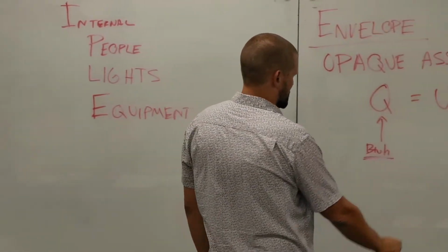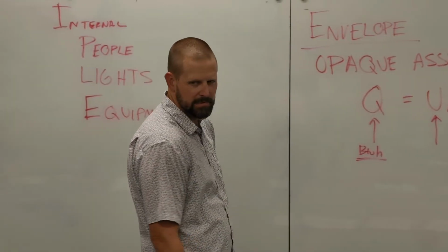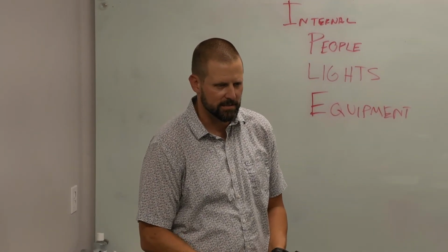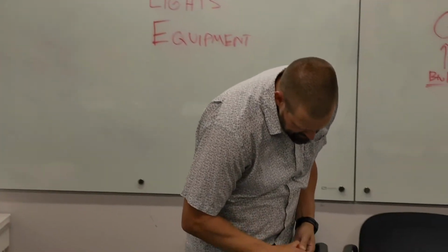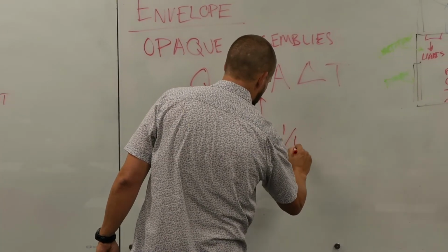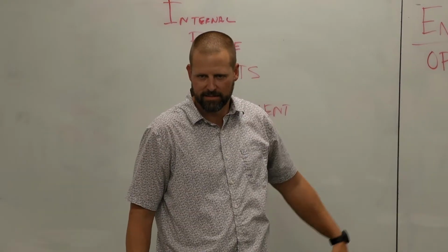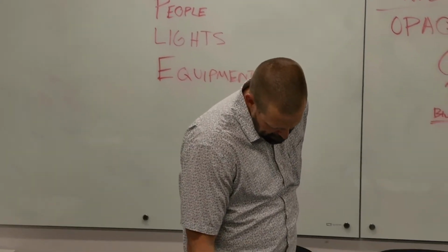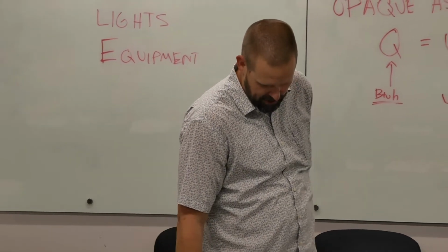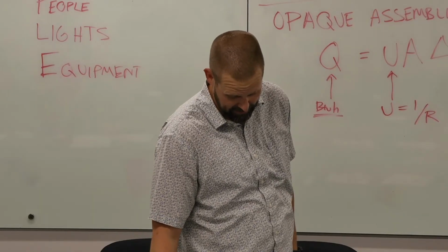What's the U factor? Universal coefficient, or I think that's some sort of coefficient. It's the opposite of resistance. Yeah, okay, well, that's good. U equals 1 over R. We'll use that later. It's some sort of thermal property. Conductance or whatever. Yep. So it's the heat transfer coefficient. It's in BTUs per hour per foot squared per degrees F.